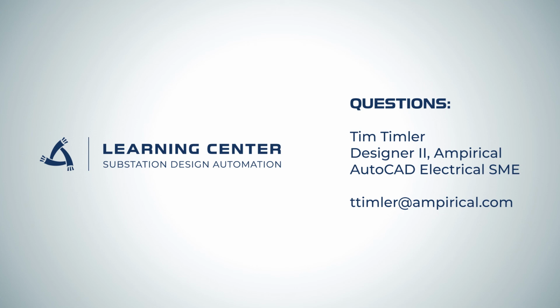The key thing to remember is that when using circuits, use a standardized grid spacing throughout the common drawing types like 3-line schematics or DC schematics. This makes the circuits flexible enough to use in any design for any piece of equipment that you might have. To add the additional power and flexibility of the SDS Add Circuit command, just follow a few simple rules for the file naming convention and insertion points, and you will get closer to achieving greater design accuracy, automation, as well as speed.